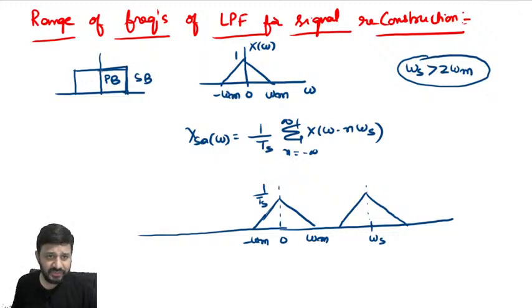Look here, this is an ideal filter. There must be a sudden transition from pass band to stop band when we are going to use an ideal filter, but these kinds of filters cannot be realized in practice. Such sudden transitions from pass band to stop band cannot be achieved practically. Why are we not going to achieve it? Let's observe within 10 to 15 minutes. In the next topic I am going to explain. So here always oversampling is only preferred.